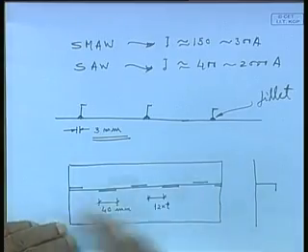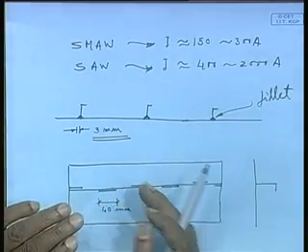So, the gap is enough for moisture to set inside and corrosion to start. So, that gives a very high corrosion, and also what will happen, the rest part of the plate is well painted. So, only a very small part is exposed. So, the corrosion rate increases, because the whole part is covered, that is not corroding, only a small part is corroding.